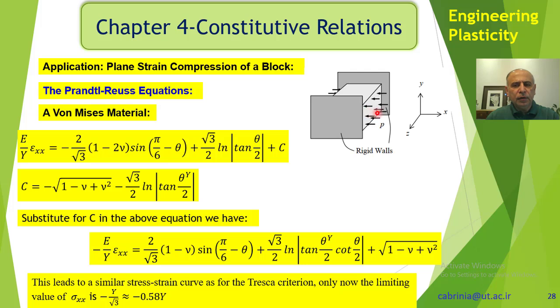Yeah. For instance, if you go from sigma y, which is the yield point, to sigma y plus delta y, then you get a certain amount of stress. But if you go as far as 2 delta y, you don't get a proportional stress, but you get more because it's due to the strain hardening. I will talk about the strain hardening effect later.